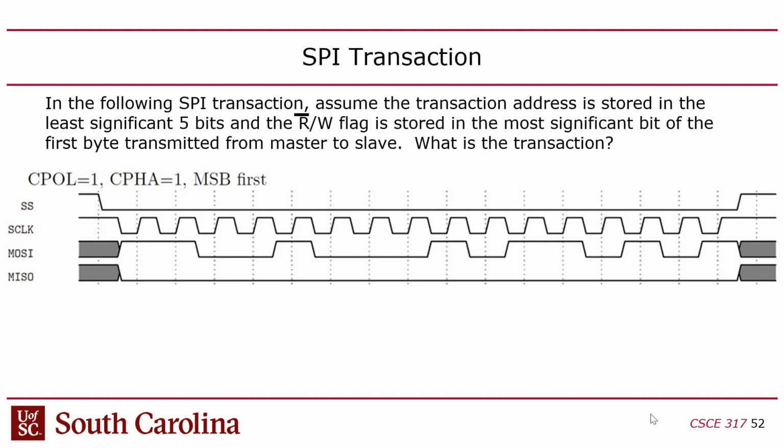Now you might be saying, wait a second, what if you want to put multiple slaves on one SPI channel, but they have different settings for CPHA and CPOL? Well, then I don't think you can. If you're going to do that, they all have to agree. But like I said, usually you don't do that anyway. In my experience anyway, it's not very common to do multiple slaves. Usually there's just two sides. Okay, so with SPI, I2C, the other protocol we're going to talk about, is a different story.